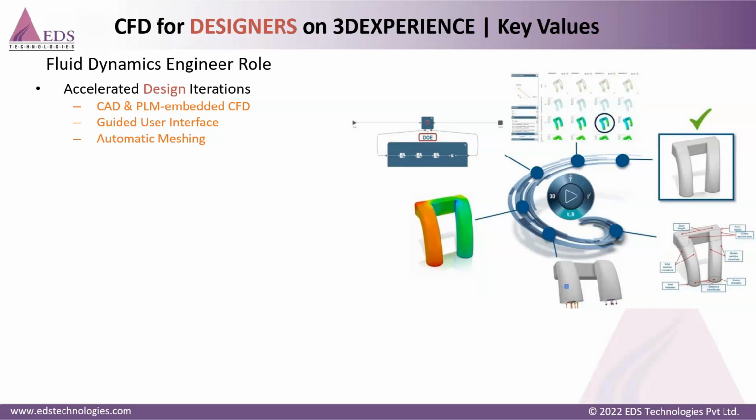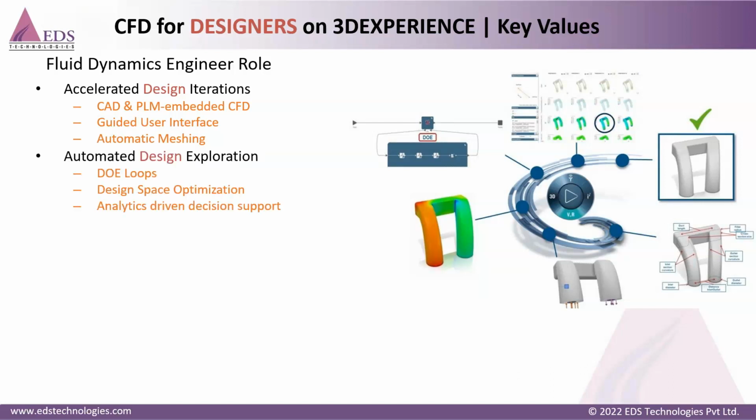On top of that, one major advantage is we have a guided user interface, which is going to guide me as a user throughout the whole pre-processing process to make sure that whatever pre-processing I am doing is proper and it is validated for the CFD processes. And on top of that, we have automatic meshing, wherein as a user, I do not have to worry about the wetted surface extraction or how I should extract it and what type of mesh I should use. Everything is automatically taken care of